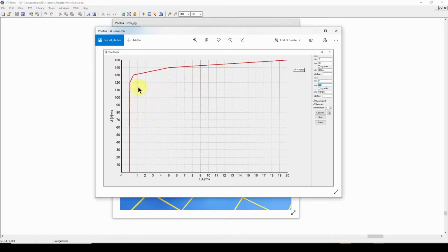But anyway, we developed this nonlinear characteristic of the 117 volt winding of the transformer. You can see on the vertical axis, it's voltage RMS applied across the winding, and the resulting current in RMS flowing into that winding with the secondary open. So there's no load on the transformer.